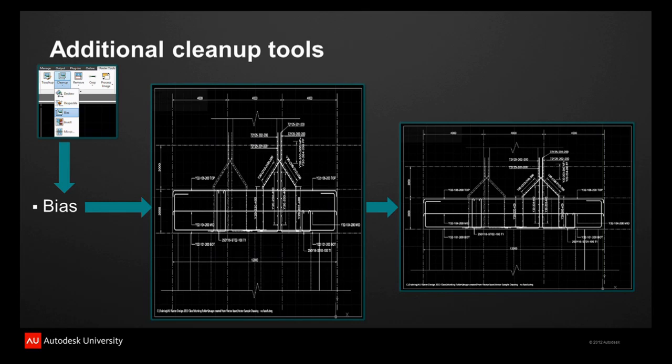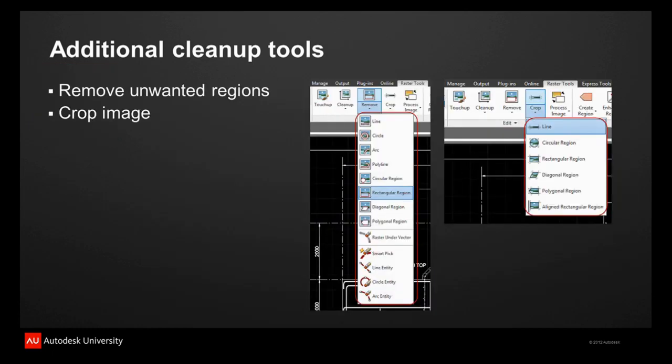So I've got a common base point, and then I was able to use the bias tool to line up these different points within the model or in this raster to get it scaled proportionally. So now I've got an image that is still just a bitonal image, but already it's scaled to proportion, and it's been de-skewed as well. There are some additional cleanup tools that I'm going to talk about. They're quite simple tools. It's basically removing different objects.